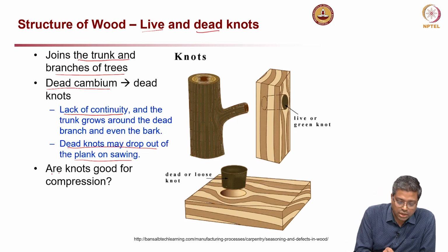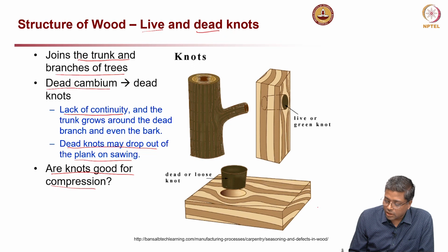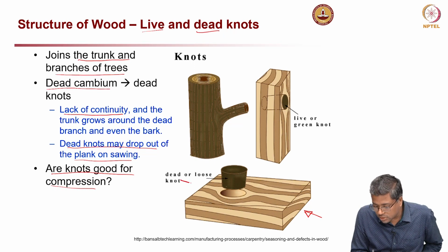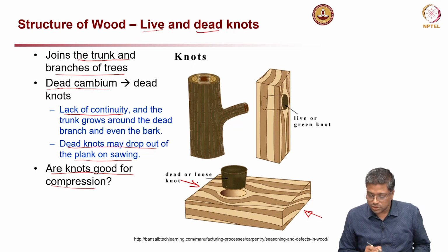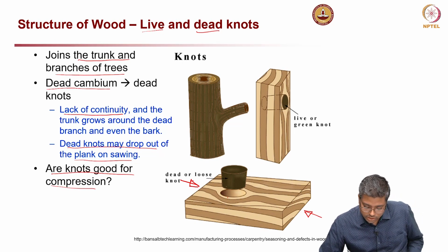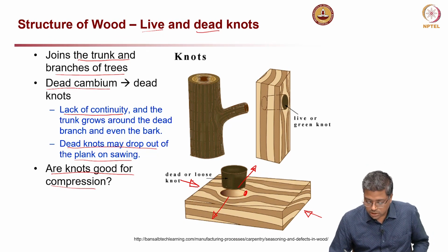Okay. So, the question here is, are knots good for compression? Now, look at this picture here. If I compress the wood in the direction parallel to the grains, there will be a lateral force generated here, lateral stress will generate here, and stress concentration will happen here.